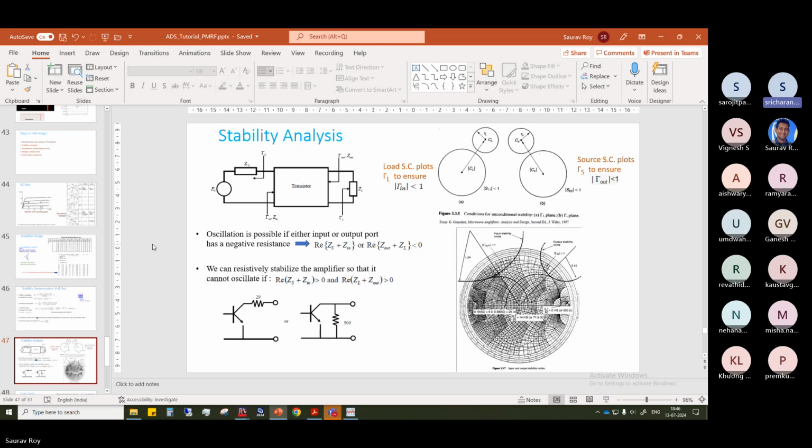Okay. Yeah, noise figure. Normally the input determines the complete system's noise figure. So if we add more resistance at the input side, the noise figure will increase. Not only will the input noise increase, it will be amplified by the amplifier, right? Yes, exactly. So that's why we are adding it in the load side. See, everything has to do with some logic, okay? So you have to understand step by step. That's why we are trying to do it in the load side, even in the shunt condition.